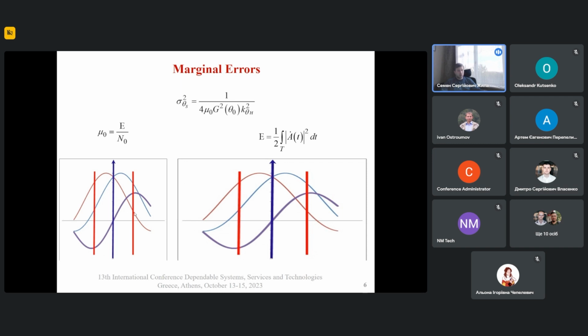And here on this slide, you can see the first example. We have two antenna patterns with relatively narrow beams, and the result of their subtraction is this function. And this function can be stated as a discrimination characteristic of the direction finder. And its slope shows the quality of our possible measurement of direction. The higher this slope, the lower the limit errors of measurements.